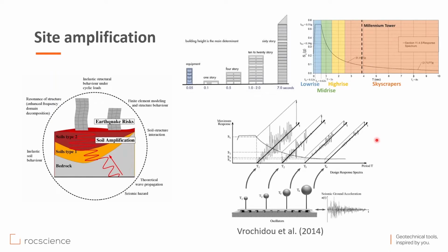Ground response effects are generally evaluated using one-dimensional models, which assume the seismic waves are propagating in vertical direction through the horizontal layers of the soil. Theoretical modeling of one-dimensional site response can generally be accomplished using equivalent linear or nonlinear analysis. Equivalent linear ground response modeling is widely used in practice to simulate true nonlinear soil behavior.